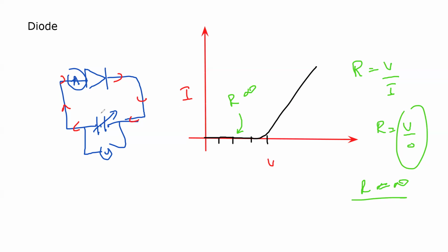Conventional current is just an assumption to explain that the direction of the current is positive to negative. But the electron flow is actually the one which happens in reality. Whenever we draw an electrical circuit, we draw the conventional current. So when the current is passing from the side of the P type, the conventional current, in that case, the diode allows the current to pass, or is in a state of on. But internally, it's not conventional current; internally, the electron flow is there. Is it clear, this part?